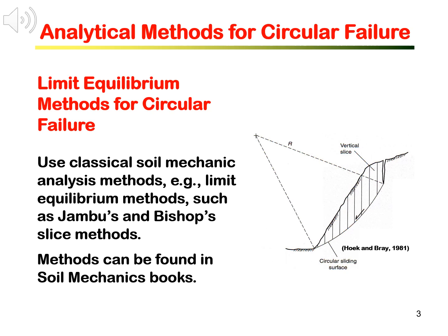When circular failure occurs, the failure is sliding on a circular failure surface that has the least resistance through the slope. Therefore, it is possible to formulate equations in terms of the sliding force and the sliding resisting force that are governing sliding along the failure plane.